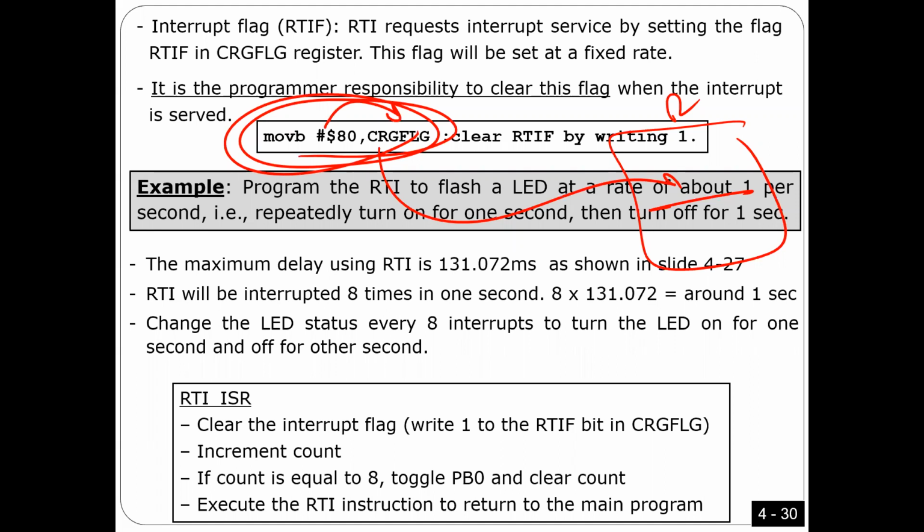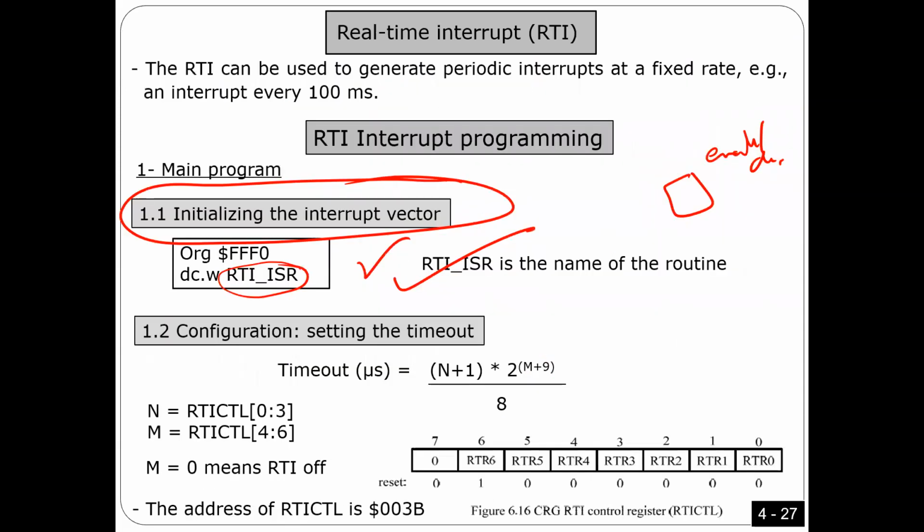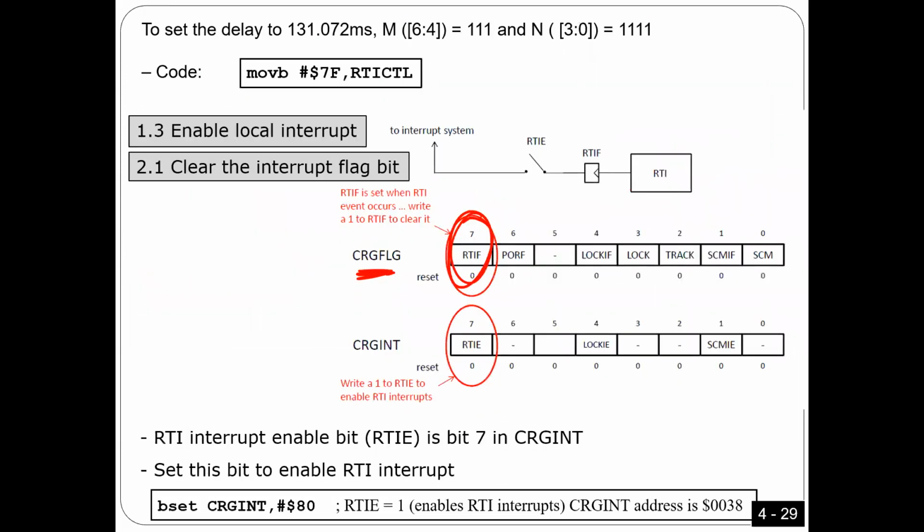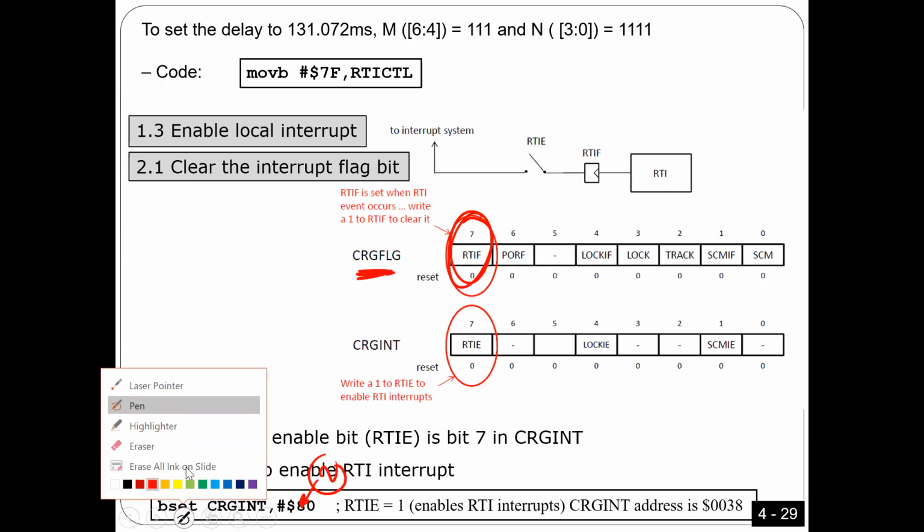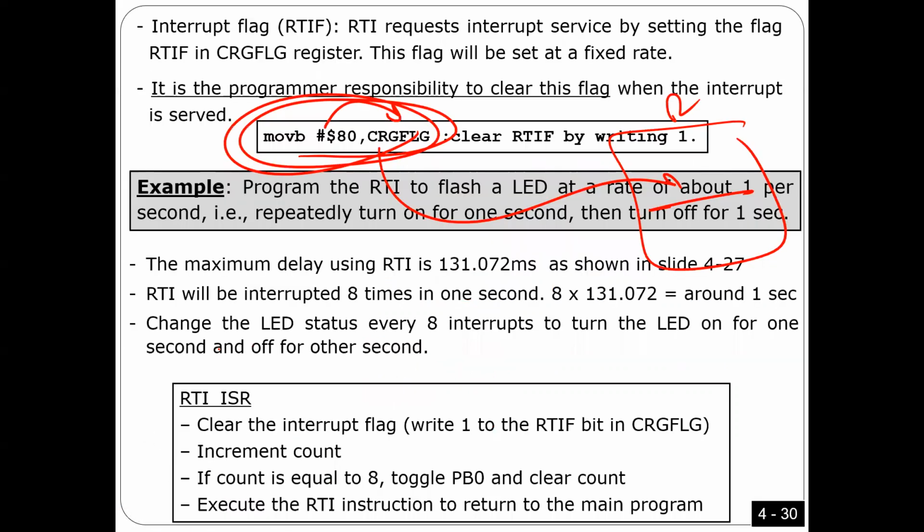So okay, what else do we have to do? Number 1, I have to program the interrupt vector. That's true. Number 2, I have to program enable. Yes, this is the second one you do. Very simple: bit set for enable, bit clear for disable. Number 3, you have to use this one inside the interrupt subroutine. What else? Again, remember, we didn't do this one in IRQ, as I mentioned last time, and this is the only exception. It is done automatically in IRQ. But when I explain the timer in chapter 5, for any other interrupt, you have to write it.